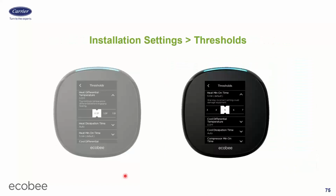The next one up is heating minimum on time. The default is 5 minutes. Once we engage the gas valve or the electric heat, it's going to stay on for this many minutes no matter what. So even if I make it to the set point, it's still going to run for at least 5 minutes. That's there to make sure that we get good usage of our heat exchanger. 5 minutes is kind of a short run time. You shouldn't be running it less than 5 minutes anyway.